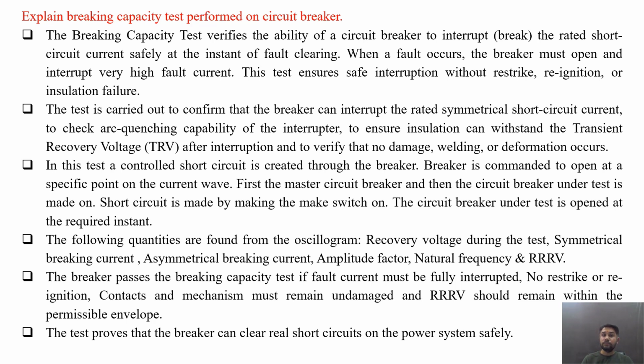or reignition, contacts and mechanism remain undamaged, and rate of rise of restriking voltage remains within the permissible envelope. The test proves that the breaker can clear real short circuits on the power system. So this is about breaking capacity test performed on a circuit breaker.